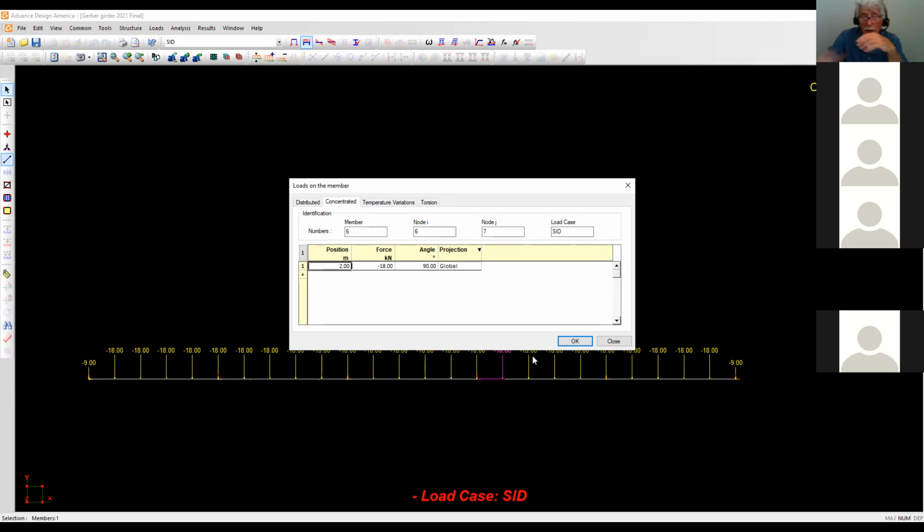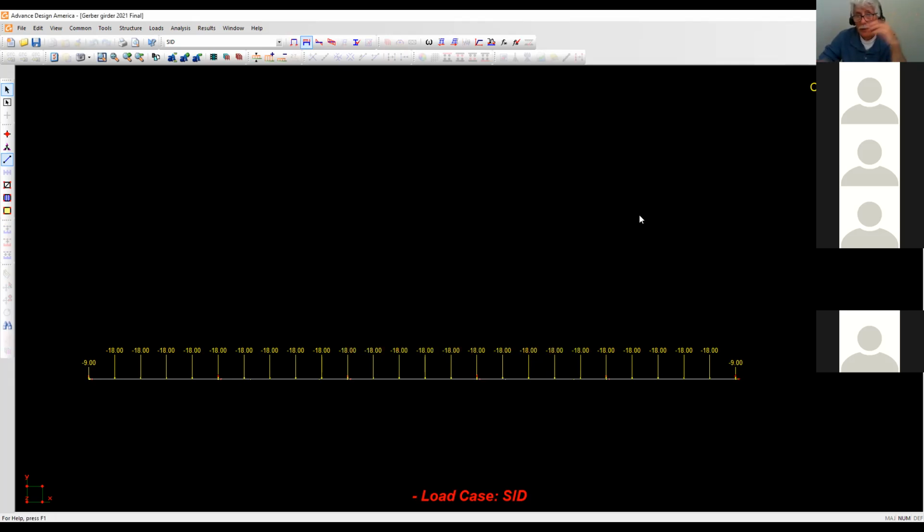That's exactly why I asked you the question. If I had thought it would work, I wouldn't have asked. I'm trying to make you understand why you can't do it that way, because each member has a specific location. That's what you have to be careful about with ADA: if I pick 2 members and start loading them, unless they have exactly the same load magnitude and load location, it would be incorrect.